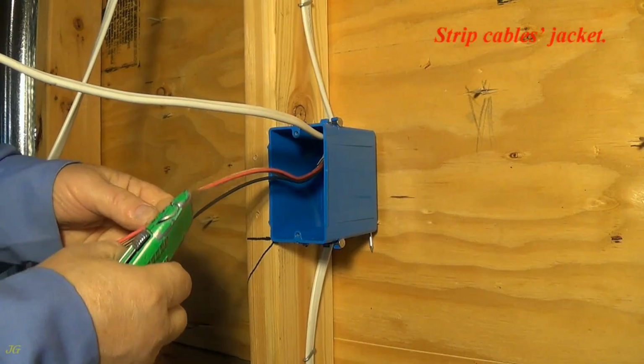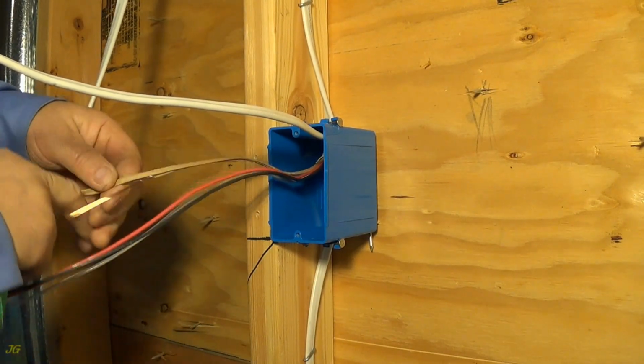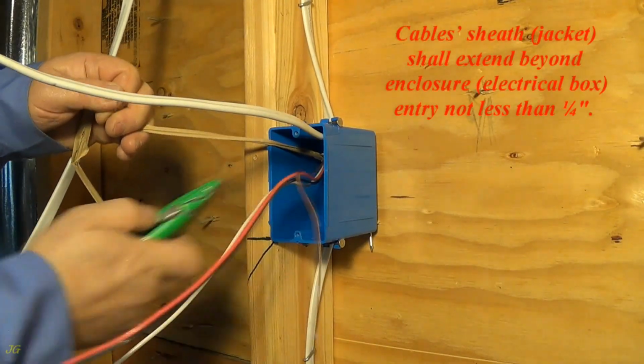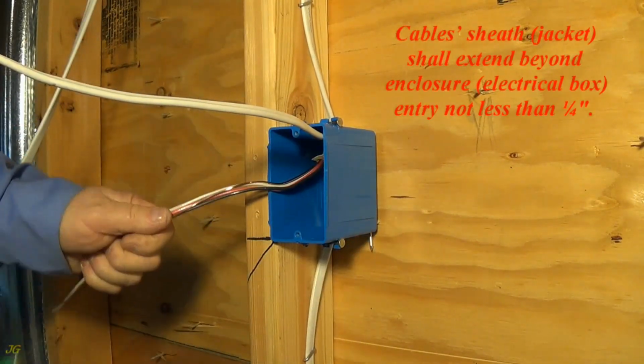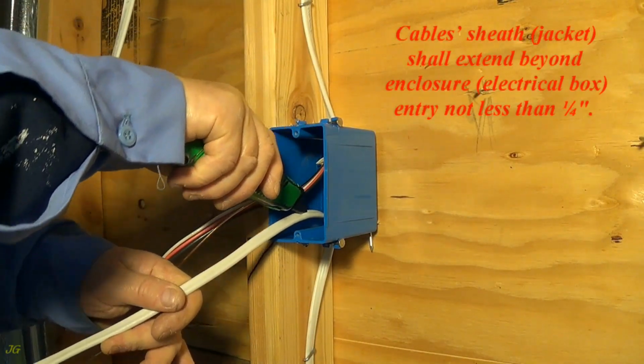Strip cables jacket. Cables sheath, jacket, shall extend beyond enclosure, electrical box, entry not less than 1/4 inch.